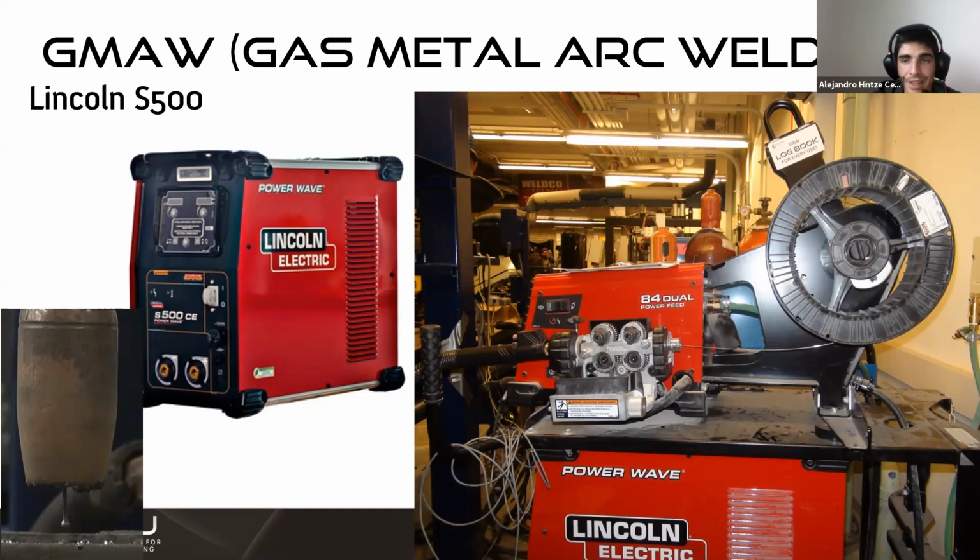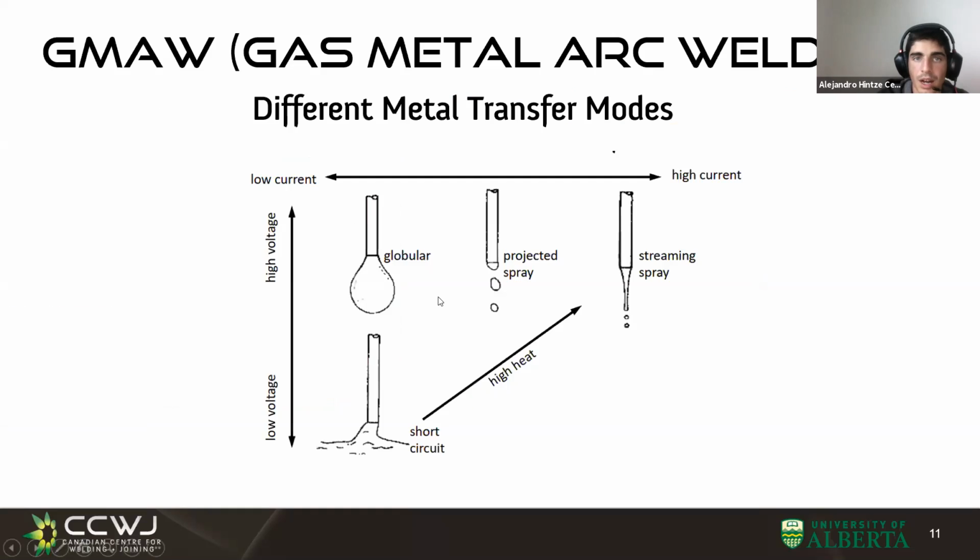This is a really state-of-the-art power source, and you can do many different things. So in this case, what we're going to look at is how, by changing the parameters, we can go through all these different transfer modes with just changing either the voltage or the wire feed speed in this case, which will change the current.